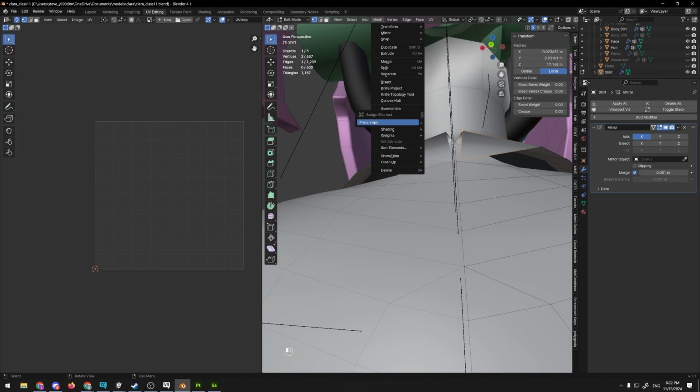I'm going to say, I don't know, something I don't already use. So, like, Control-Shift, backslash. Backslash doesn't work. Control-Shift, plus. You get the point. Or it did assign it, so Control-Shift equals. Perfect. So that's an easy way. You can do this anywhere on the UI effectively. You can just right-click and assign a shortcut to something that doesn't already have a shortcut in Blender.